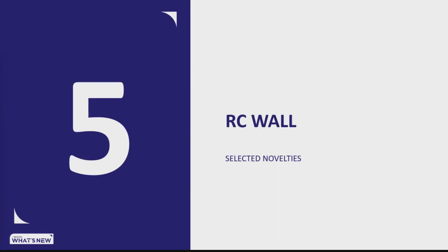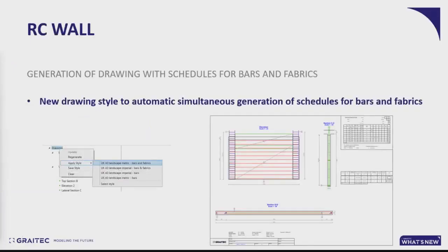Yes, the next module is a concrete wall module. First improvement is related to drawings. When we generate drawings for walls, by default, a rebar schedule is generated. But if there are reinforcement meshes, reinforcement fabrics, then we have two options. Either, as before, the schedule for meshes can be separately generated and added to the drawings, or we can use a new drawing style that allows automatic generation of schedules for bars and fabrics. So both schedules are generated at once then.